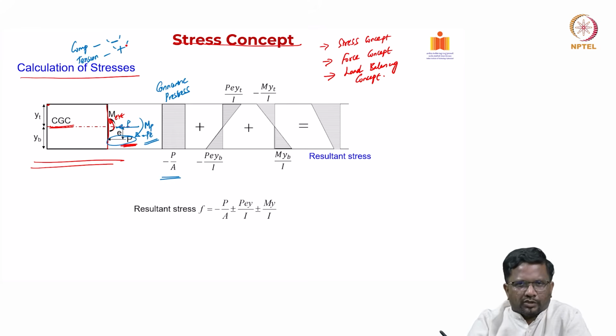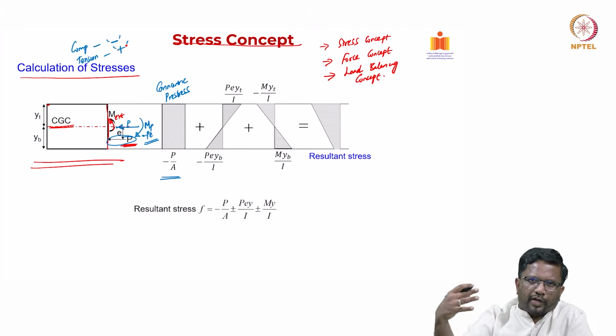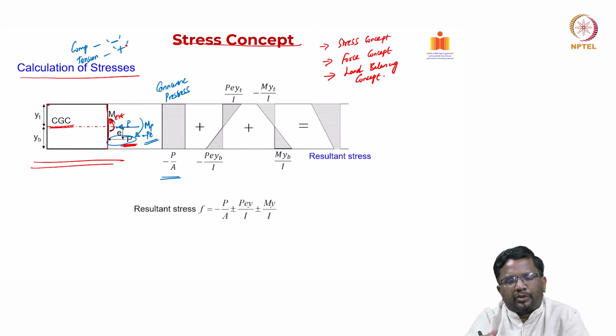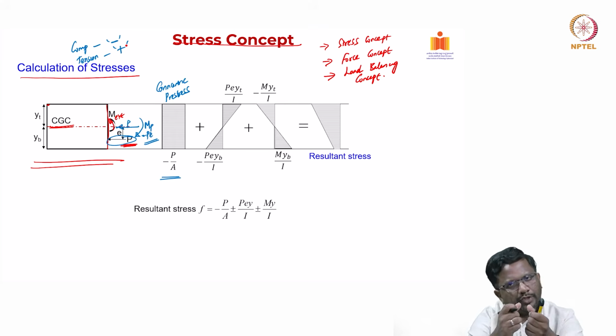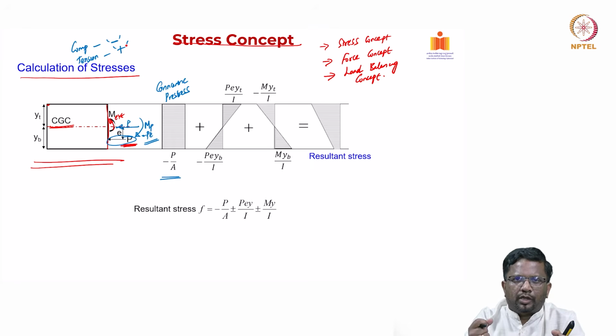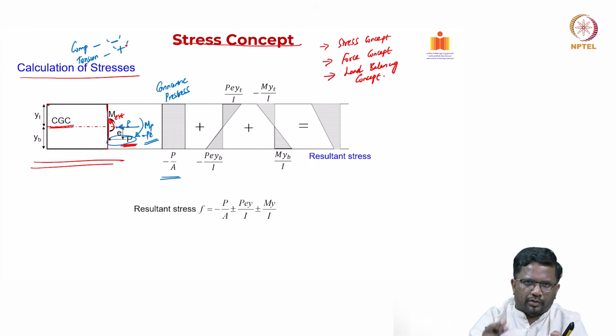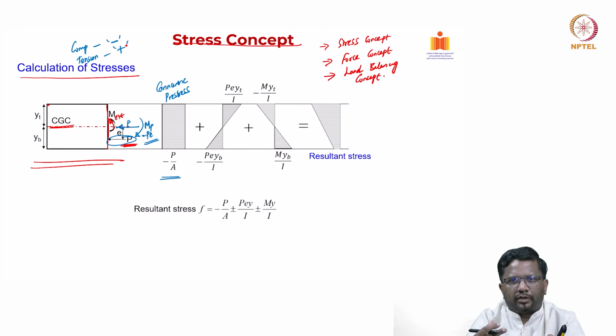So, what are the stresses that are going to come from the applied axial compression? Please also note that we are looking at the effect of steel on the concrete. Steel, pre-stressing steel, we are stretching it. When you stretch it, it is always going to be in tension, but because it is in equilibrium with the concrete at that section, they are all connected together, right.